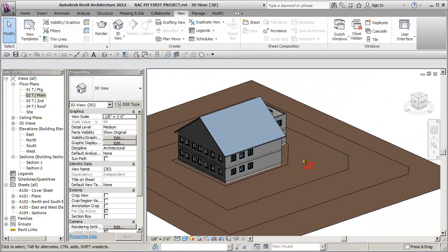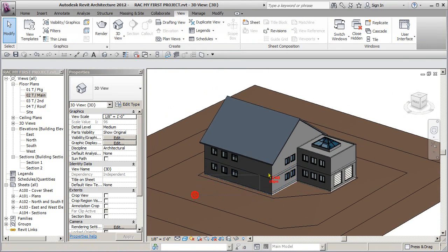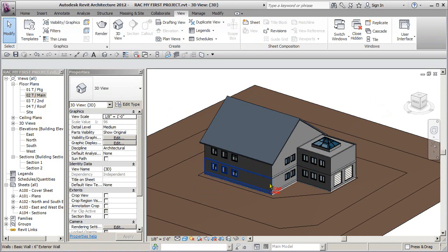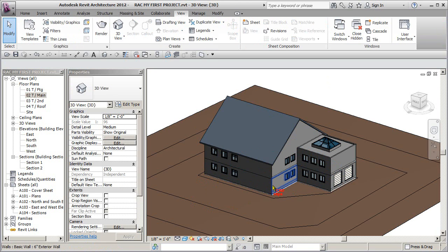So in this case, you can use Tab to remove stuff. Watch, I'll do it again here. Do a big window box. I'm going to hover over this lower wall. I'm going to go Tab, and then holding my Shift key in, now click. As opposed to just creating a selection set where I just hit Escape, it's hover, Tab, select. That would select them. I'm using the hover, Tab, Shift, select.